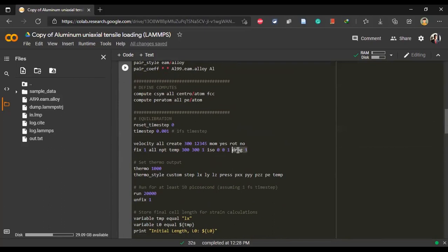And the drag one is because there might be some oscillation. I mean, LAMMPS can never get to an exact value. It always oscillates around the exact value. Suppose you have provided a temperature of 300 Kelvin, and then it may not always give exactly 300 Kelvin. It may go to 301, 302, or maybe 320. It will oscillate around a value that's almost the same. So I'm using a drag command so that it will be close to the exact value.